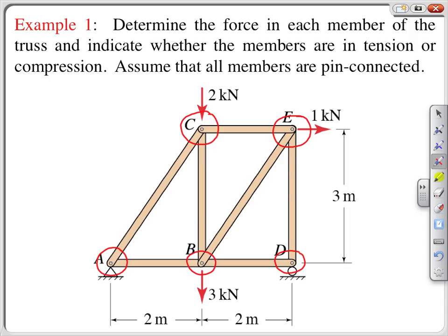One approach is to draw all the members as though they're in tension, even though they won't be, and then interpret positive numerical values as tensile and negative numerical values as compressive. You can always think of a negative tension as a compression.